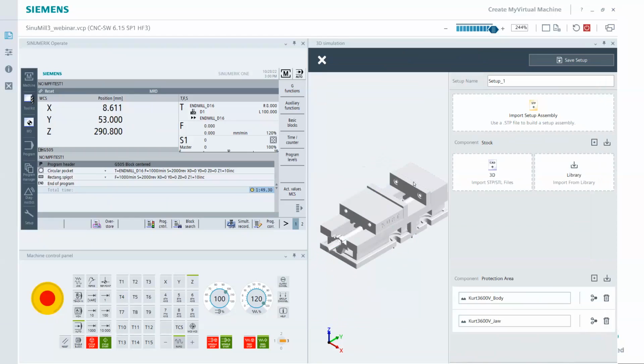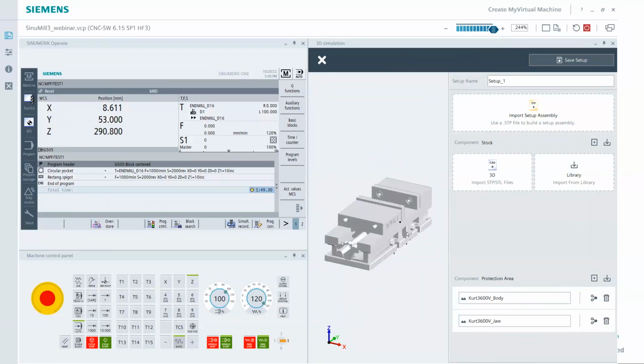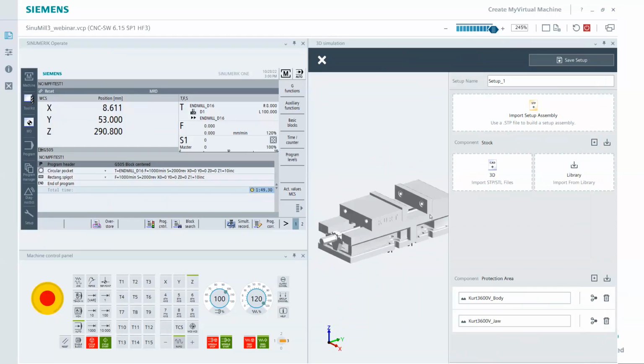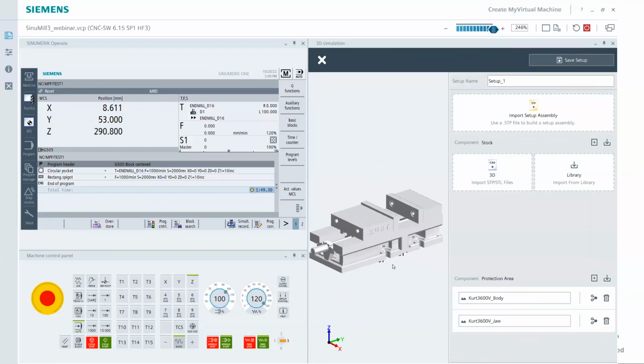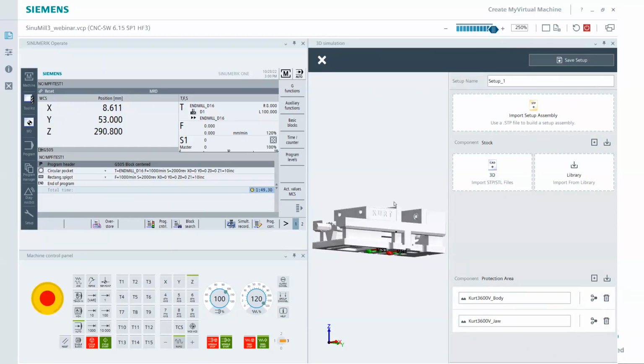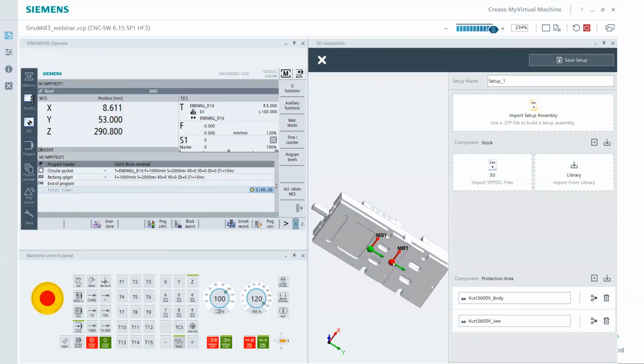So it keeps me from having to make a whole bunch of separate work holdings. I can just keep using this vise over and over again, and just moving my jaw around. Now, one of the things you're going to want to try to do, to minimize the amount of moving around in space you have to put this vise, is have a pre-defined location on the vise as your zero datum. So mine is this one right here.